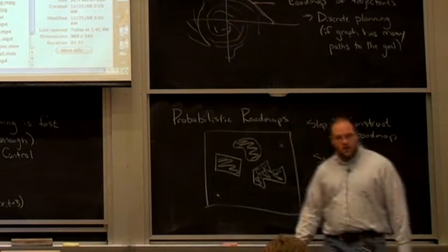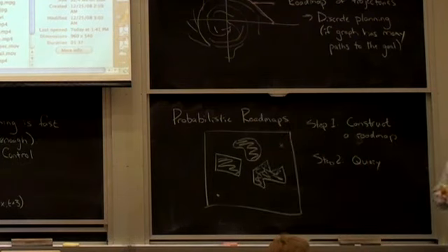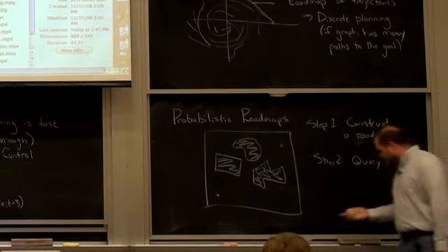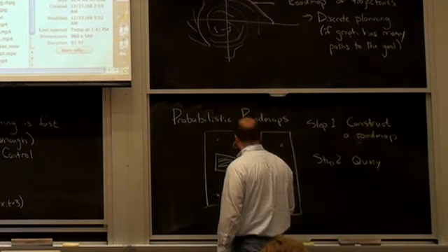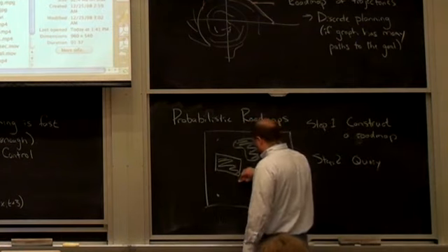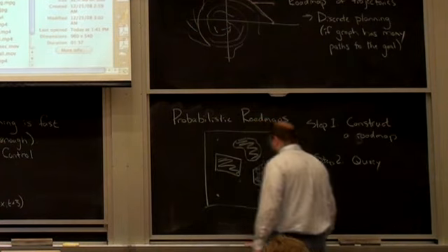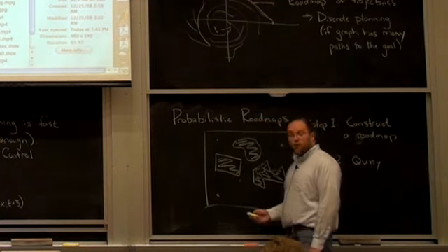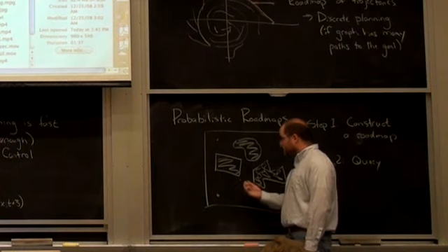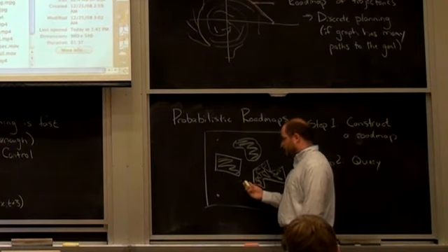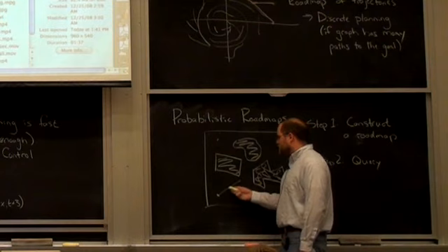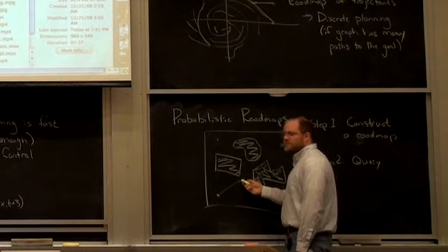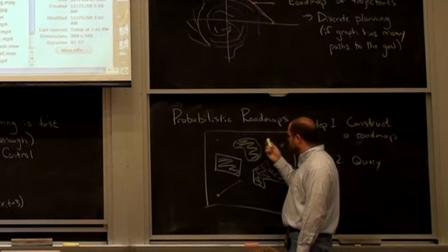So before I even start to solve the first problem, let's just drop in a lot of random samples throughout the space. Choose uniformly over the space. Every time I add a point in the configuration space, I try to connect that new point to the n closest points with simple strategies.